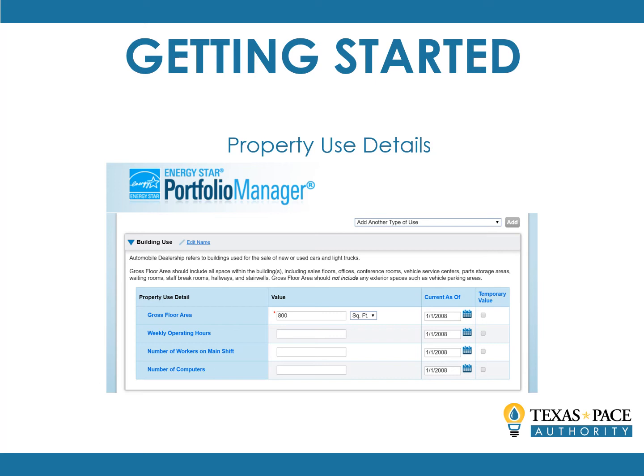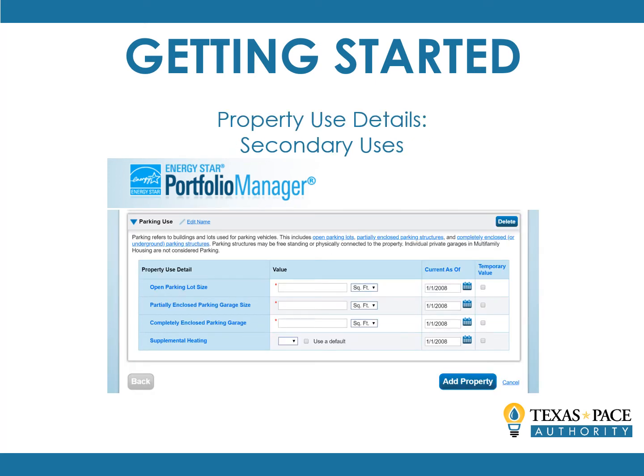You'll have an opportunity to add another use type. So if you have a property that is partially commercial office and partially retail, the primary use type will already have been added. Here, you will add the information that pertains to the secondary use of the building. Based on your building usage type, it will prompt you to add some other relevant information. In this example, we have a car dealership, so Portfolio Manager is asking us to enter information about the dealership's parking lot. You want to make sure that the primary and secondary use type square footage add up to the total square footage that was inputted at the start of the process.